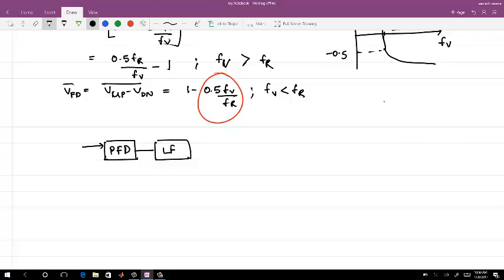Type 1, type 2, or what? Integrator. So we have to use an integrator in the loop filter and a VCO. So this will detect your frequency and phase both. Let me say F in and F out. This is the first one which you can think about once we know the phase frequency detector.